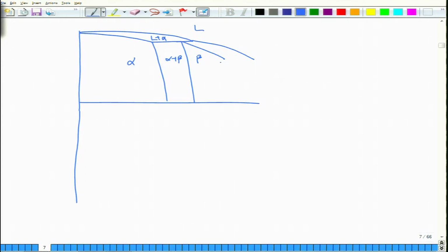So, the beta phase field goes very narrow somewhere here like this, and you have then a transformation to alpha plus beta prime, and this is about 47%, and this is about 37%, and this edge is about 45%. So alpha and beta brasses lie between about 37 to 45%.